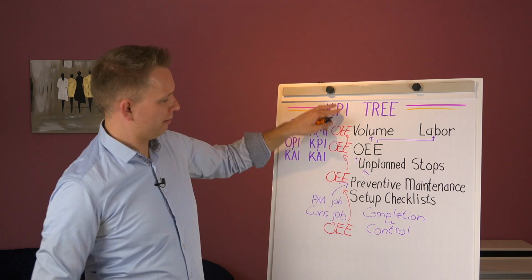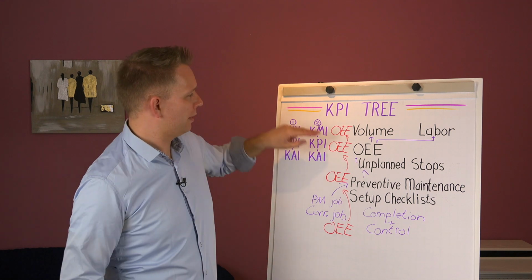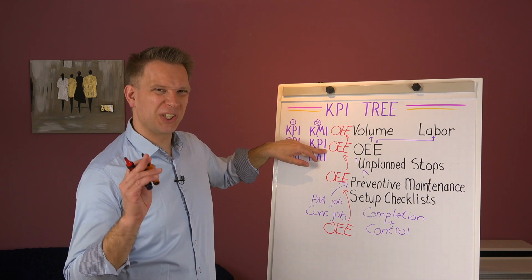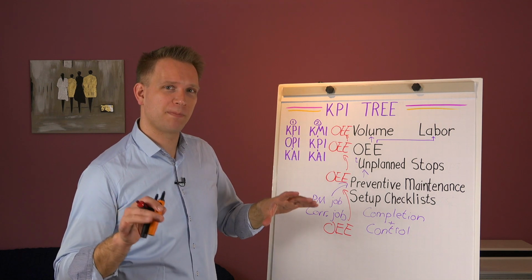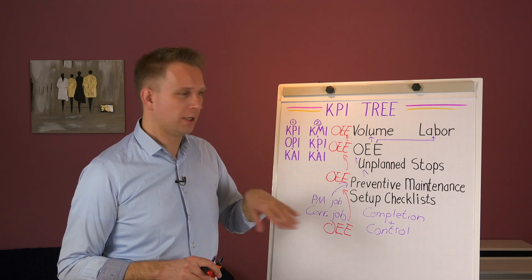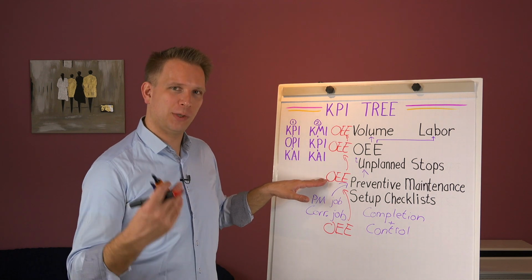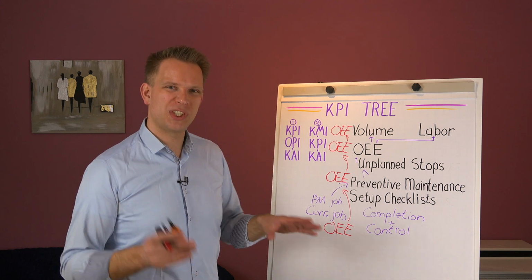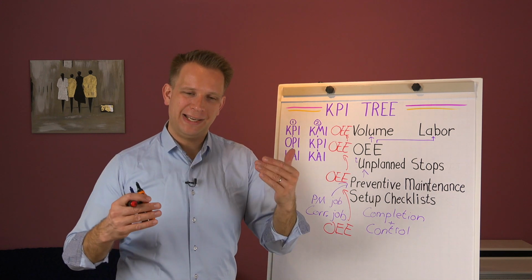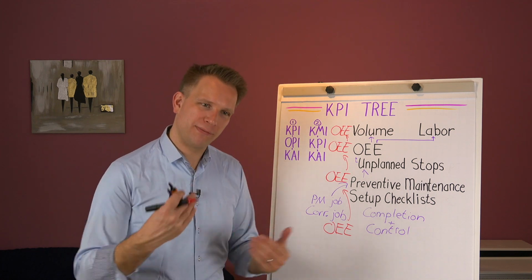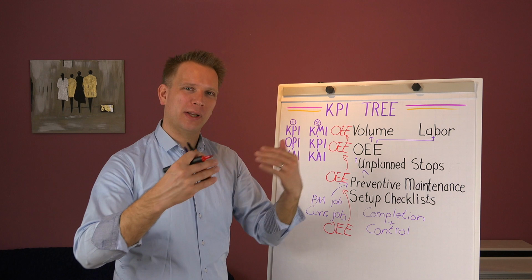And like this, we have a KPI tree of OEE of the company, OEE per plant, which is nice because we can compare it between plants. Then OEE of every line in our company that we, of course, will show daily and weekly and monthly. And every shift will see their own OEE and they can nicely compare. And you get this challenge, you get this way of comparing and going like a race.